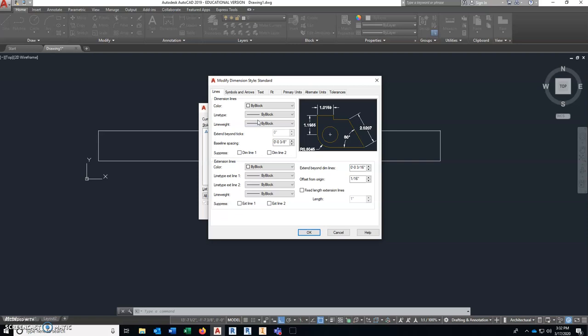Well, what that also means is I know my standard text size is between a 1/16 of an inch and an 1/8 of an inch. Well, if I plot something in the drawing at a 1/16 of an inch, when I print it, I'm scaling it down 48 times. So a 1/16 of an inch or an 1/8 of an inch shrunk down 48 times becomes invisible. It becomes a dot.